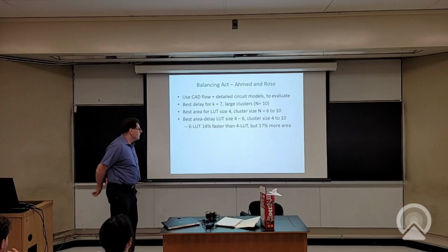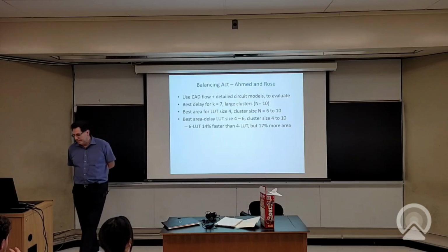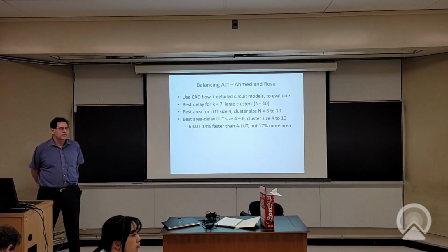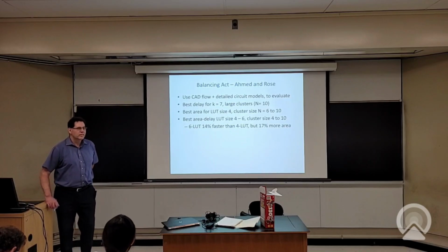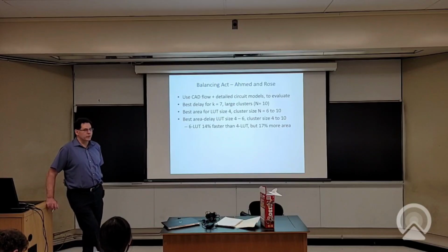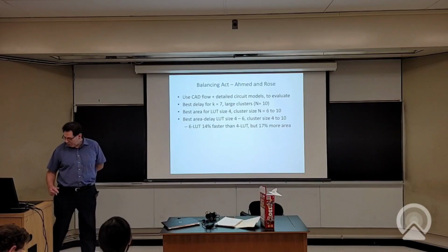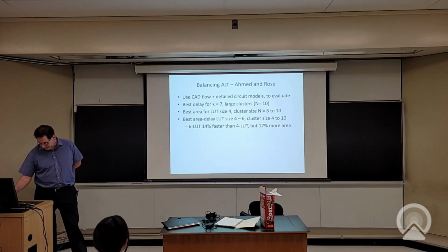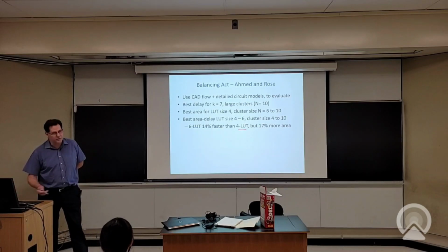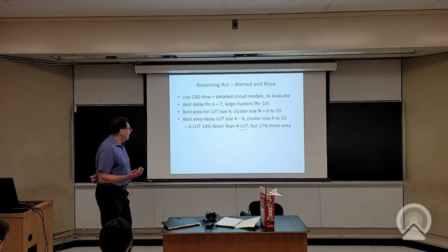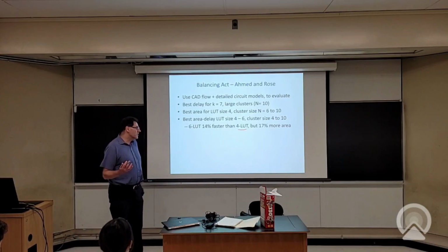Partly. Altera and Xilinx want to be faster while someone else wants to be reducing area. I know Microchip always wanted to be better on power, so that would reduce area. Power does, to first order, correlate with area. So if you care more about power, then the fact that the 4-LUT is more area efficient is more compelling to you. So that's one reason.